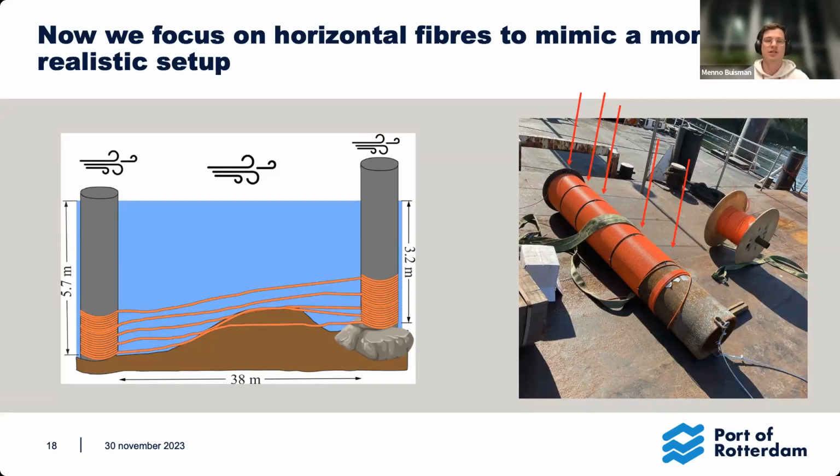Now, this schematic setup we created after a dive inspection, and the dive inspection revealed that we have about 2 meters here from the pole to the mud anomaly, and that here it was about 32 meters to the mud anomaly, and that we had 2 fibers here laying on top of this anomaly, and 1 was buried in the sediment. And our top 2 lines, they were completely suspended in water.